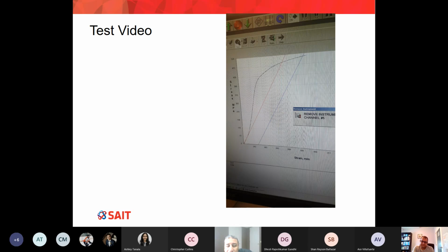It's a difficult one, because why did this happen? Theoretically, the black should go along the red. However, I can tell you, due to maybe a problem with the testing, the initial behavior has a kind of slippage. Okay, so this slips. Maybe there is dust or dirt on the surface of the specimen, or a little bit of rust, where you get kind of less strength. But as soon as this is broken, you get the real behavior of our material.